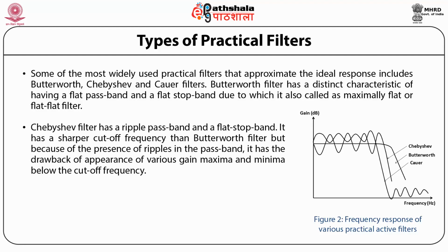It has a sharper cutoff frequency than Butterworth filter, but because of the presence of ripples in the passband, it has the drawback of appearance of various gain maxima and minima below the cutoff frequency.